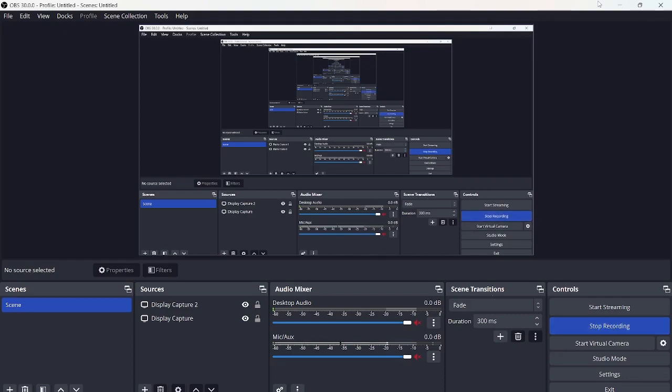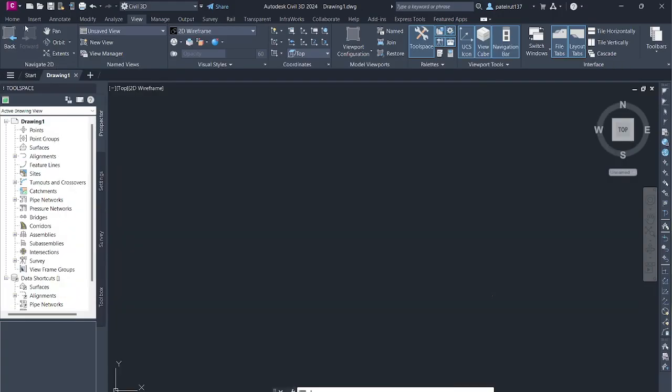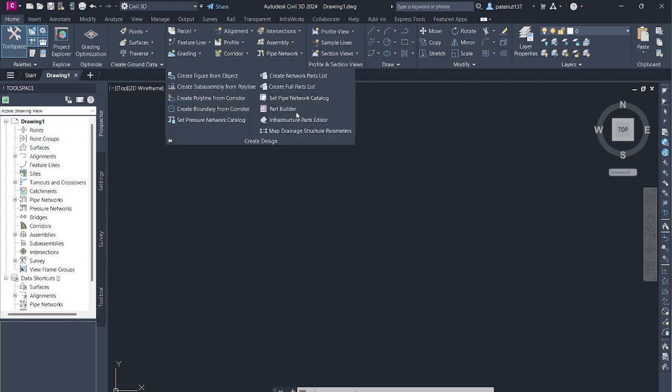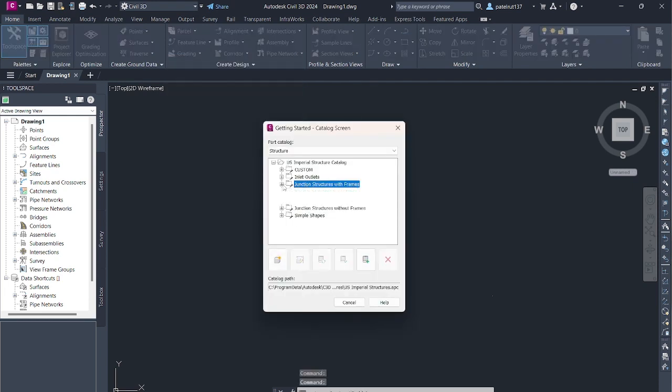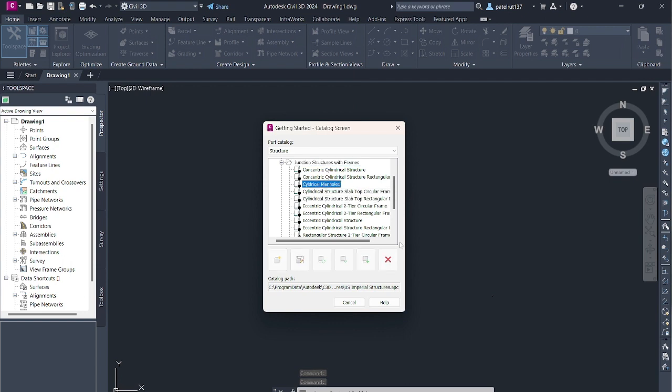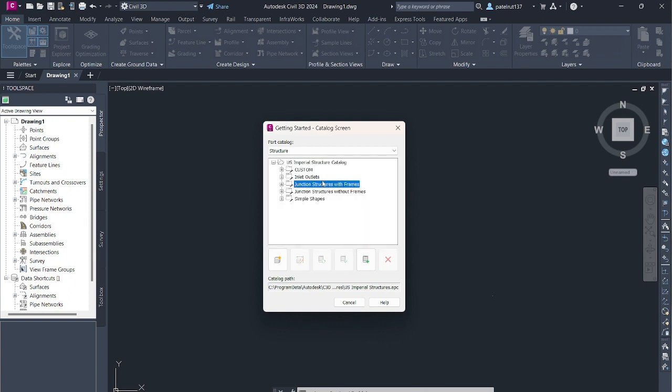Change your view to a front view. The stack of work planes and the transitions created in step 17 are displayed. Following the same methodology for the first batch of transitions created in steps 16 and 17, add transitions between the top of riser 2 profile and the smaller top of barrel profile, then the larger top of barrel profile and the bottom of structure profile.